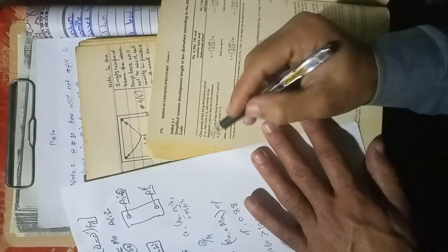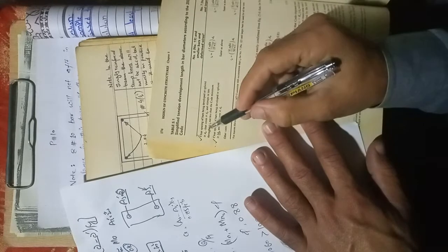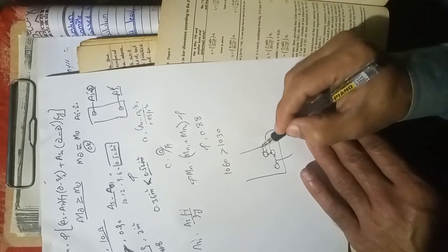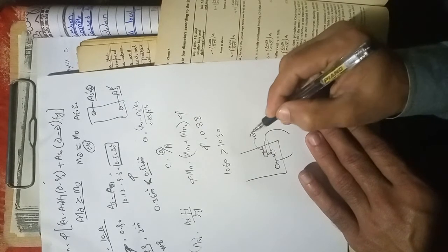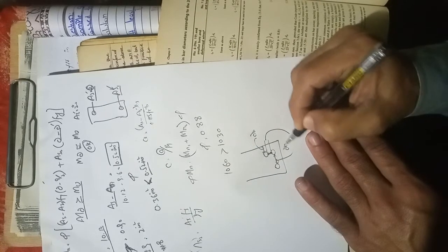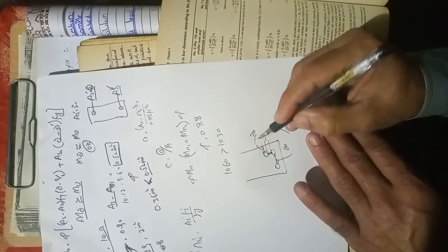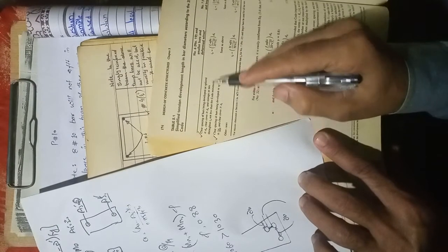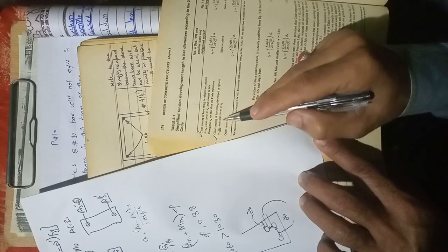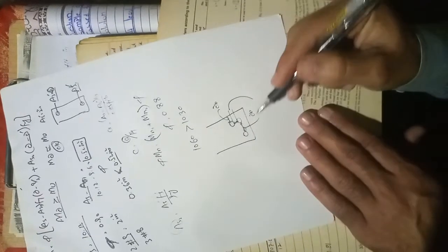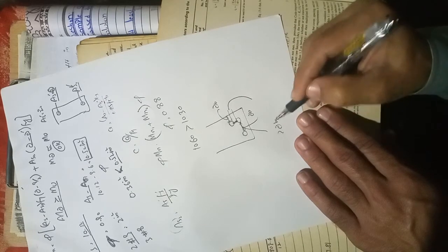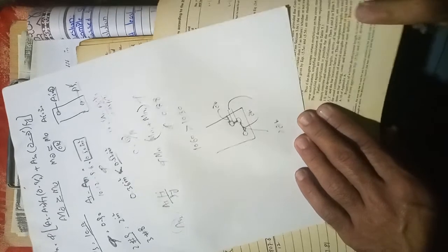We have two conditions. In one condition, the clear cover and the clear spacing between bars should be greater than the diameter of the bar. In the second condition, the clear spacing of the bars being developed or spliced should be greater than 2 d_b, and the clear cover should be greater than d_b. Means in the second condition, the spacing of the bars should be greater than 2 d_b. So what is the effect?